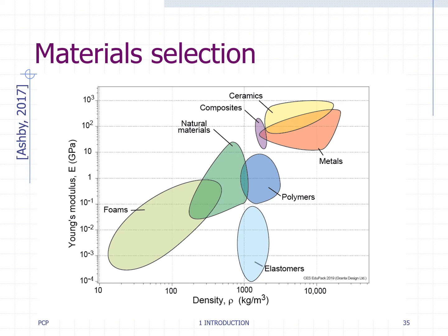There are different approaches for selecting materials. A useful method is plotting material property charts, sometimes called Ashby charts, with one property on one axis and another property on the other, both in logarithmic scales. In those charts, material groups are merged, with all the ceramics, for example, having similar values. They can be used to perform material selection for new designs or to identify trends in properties and the relationships between them in a highly visual way.